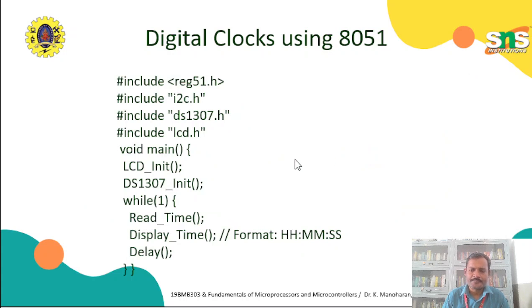Look at this program. I am including the header file reg51.h for the 8051 microcontroller. I am including the I2C protocol header file, I2C.h, because we need to connect this RTC through the I2C protocol. I am including DS1307.h, the header file for the RTC, and LCD.h for the LCD display. These includes are useful for us to easily write the programs, because we do not need to write every function ourselves. We can simply call the functions and use them.